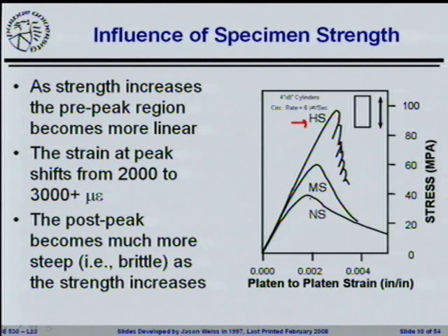All right, so to give you an idea, this is about a 5,000 psi mix. This is about a 10,000 psi mix. This is about a 15,000 psi mix. To put those in units that we may be a little bit more familiar with. Okay, this is an incredibly high-strength concrete. This is a good quality concrete. This is something you're going to see every ready-mix producer doing. The portion of the diagram that is directly linear, here you might see it might be 50% for your normal strength concrete. For your high strength concrete, it's much, much larger. 80%, 90% of the system is linear.